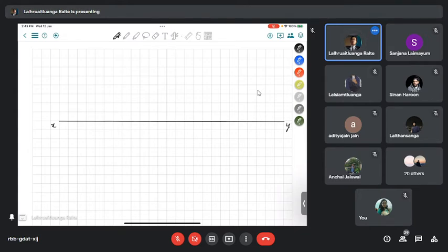Our first condition says that our square pyramid is resting on its base on the HP. That means it is not floating above the HP. So I am going to have the pyramid base on the XY line itself in the front view. Now, when a side of the base is parallel to the VP, I can start by making a line parallel to the VP.